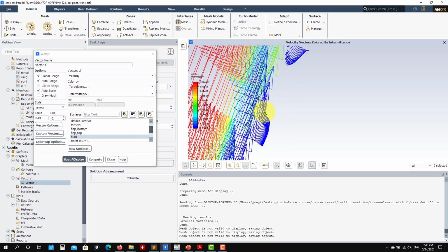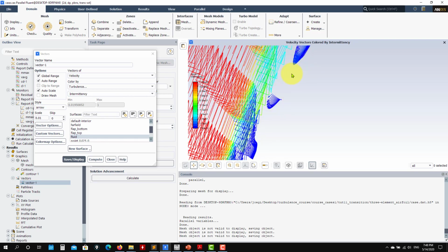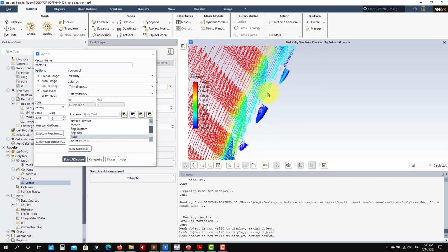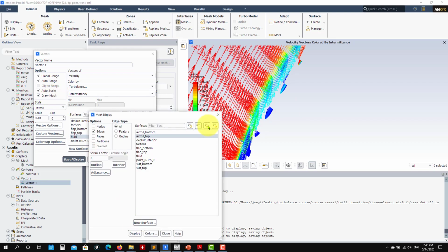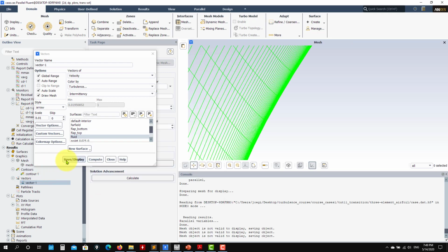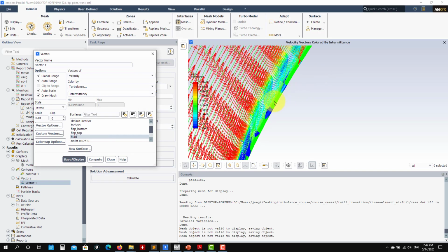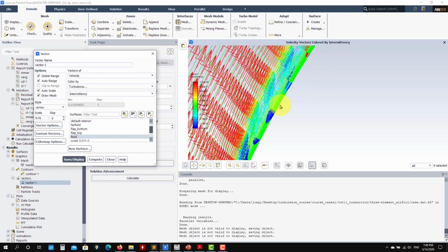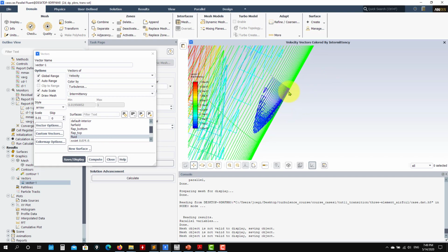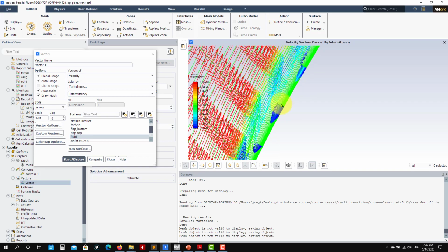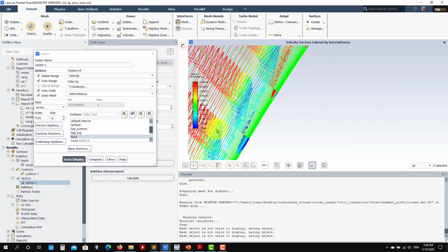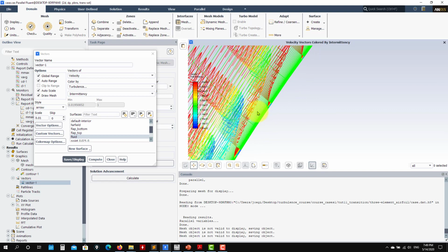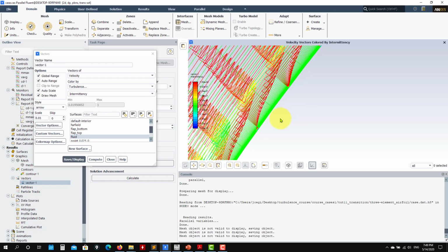See that the flow is attached, and suddenly you have the separation, and you have this bubble. These recirculation regions are very difficult to capture. You can guess that you need very fine meshes, and not only in the normal direction to the wall, but you also need them in the streamwise direction to capture it. See that here you capture it very well in the normal direction, but in the streamwise direction it might be a good idea to subdivide the cells to get it well, if you want to precisely pinpoint the dimension or the reattachment point of that separation bubble.